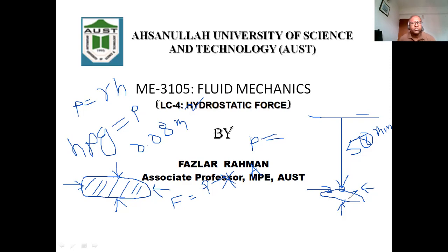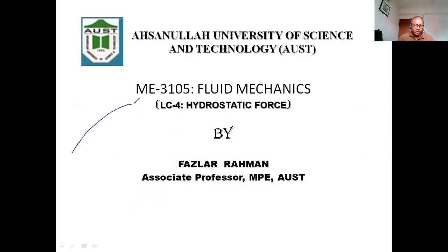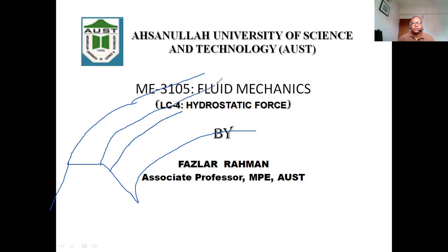So my intention is to explain the importance of the equation P equal to H rho G. Another thing is that fluid pressure is a very important thing. If you do not calculate fluid pressure properly, you cannot design some structure which will be submerged in the water or floating in the water. For example, you cannot design a dam. Say you have a dam and this side has water. So if you design that the maximum water level in the front side will be this much height, then you see